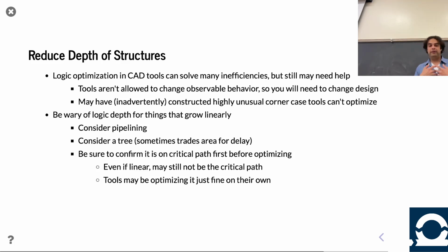I shared an anecdote before of how, in Chisel, if you use a Vec, at least in the old version of Chisel, the new version with Chisel 7 and FIRTool does better with SystemVerilog output, a 500 element Vec is going to lead to 500 muxes. Literally checking, is this element 0? Is this element 1? Is this element 2? Is this element 3? If it is, it gives you the element, otherwise it passes down this mux.